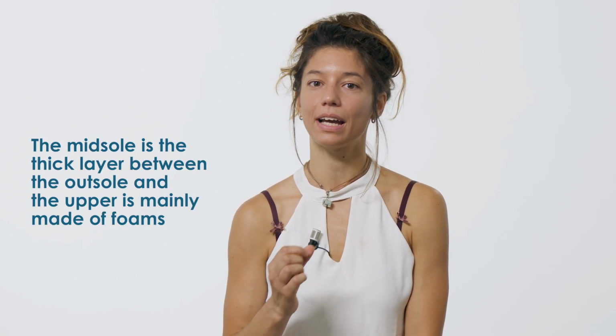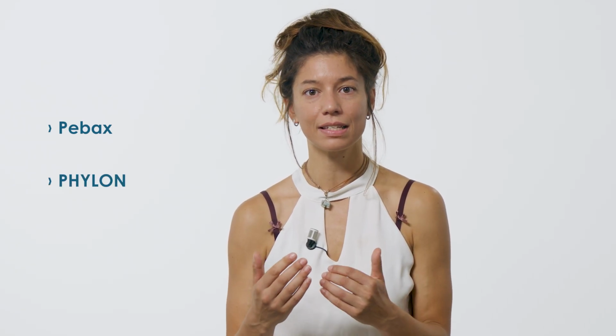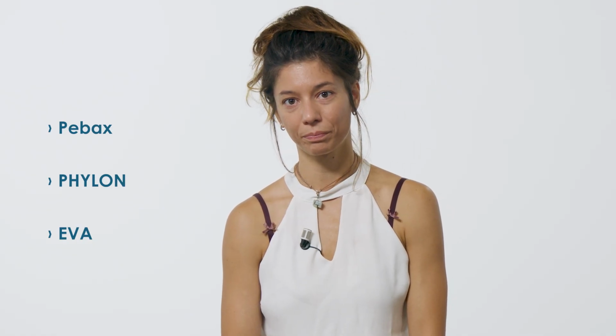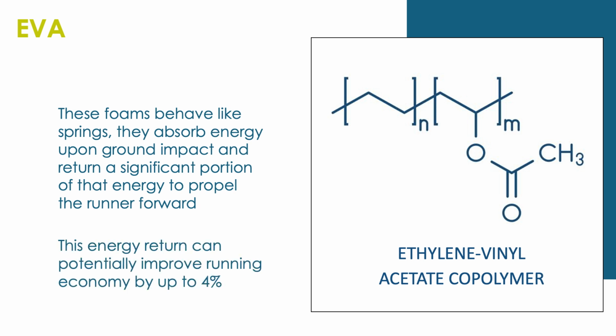Let's begin with the midsole. The thick layer between the outsole and the upper is mainly made of foams. Recent advancements have led to lightweight and elastic materials like Pebax, Phylon, better in damping elasticity and durability, and EVA, ethylene vinyl acetate copolymer. These foams behave like springs. They absorb energy upon ground impact and return a significant portion of that energy to propel the runner forward. This energy return can potentially improve running economy by up to 4%, especially over long distances.